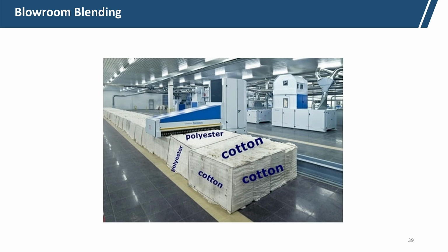Here you can see the fibers are arranged, like polyester and cotton, depending on our requirement, and this plucking device takes the fiber from the top and travels from one side to another, plucking the fibers continuously, and that is why it maintains the blend percent.